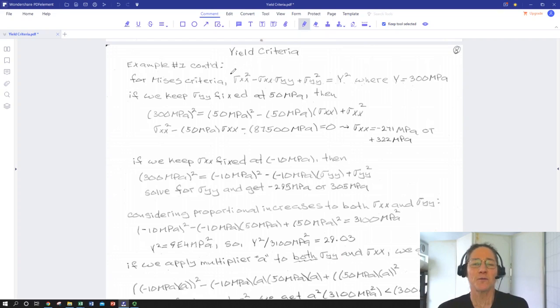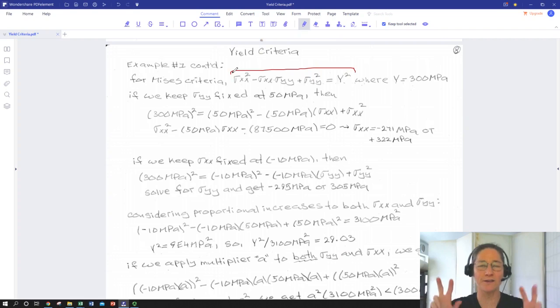So we know that from Von Mises, if we're looking at plane stress, we've shown in our derivations that this combination of expressions for applied stress constitutes at least a simplified version of our J2, our deviatoric strain energy. We've only got stresses in 2 directions, and we have no applied shears.